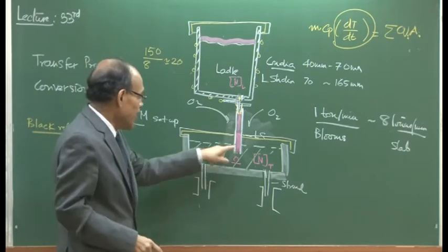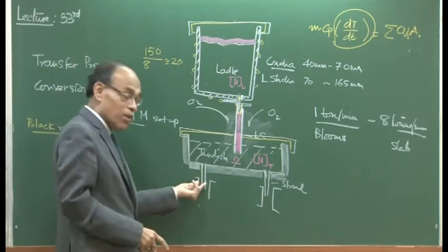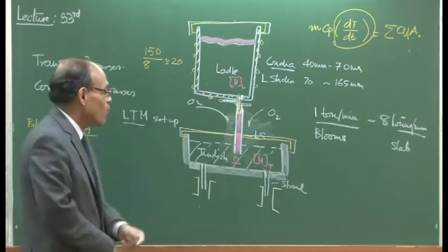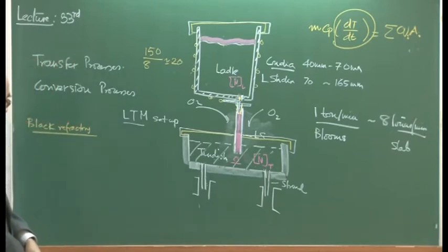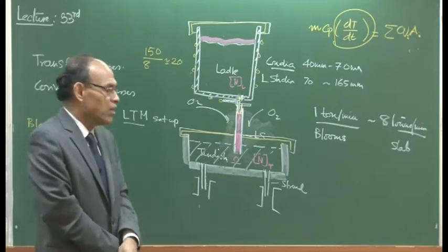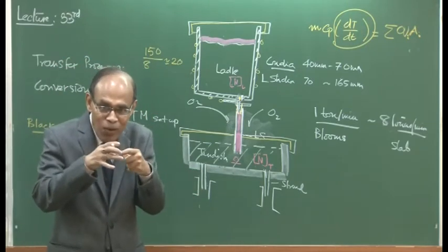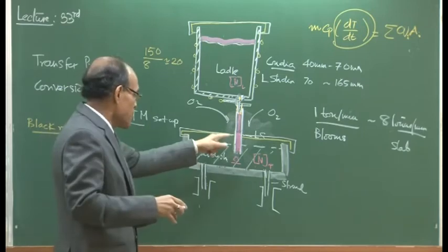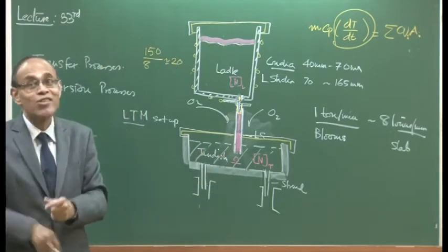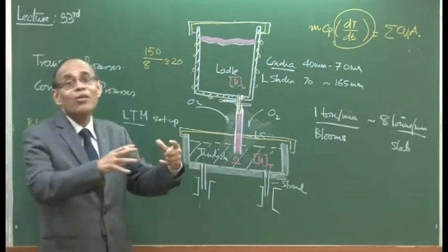So, one inlet and one outlet, which you call one strand, and the maximum I know is a 16 strand tundish operating somewhere in China. In India, I think the maximum number of strands is in a billet caster. As the section size becomes smaller and smaller, to maintain the same throughput rate, because the plant productivity has to be maintained, we will require more number of strands.